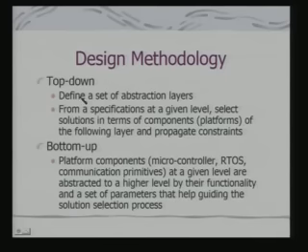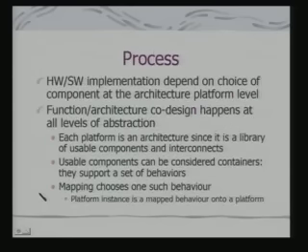Here we are coming from a top level abstraction in terms of functionality, and from the bottom we are going up in terms of raw components, the microcontrollers, the basic RTOS, the communication primitives, and the bottom up process goes through a level of abstractions, so that these two have to match. If they do not match, then we cannot really do an implementation. So a design methodology becomes a combination of a top down and a bottom up process.